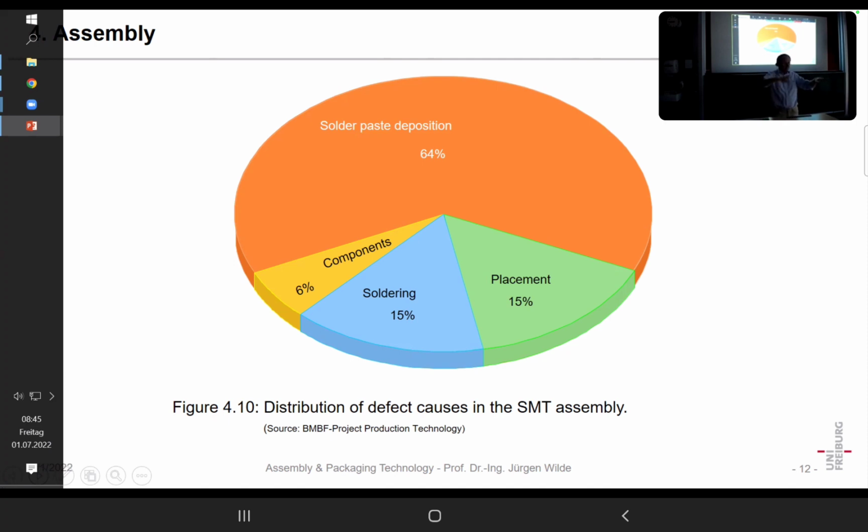The screen is above the board, and it is pressed down, and when the squeegee goes away, the screen hops off, in German, Absprung. And so the stencil is put on flat onto the substrate, and the stencil is made of metal, while the screen is metal wires covered with photoresist.